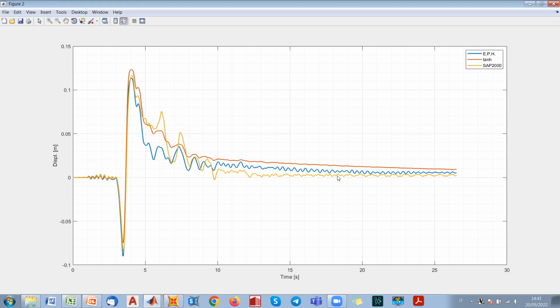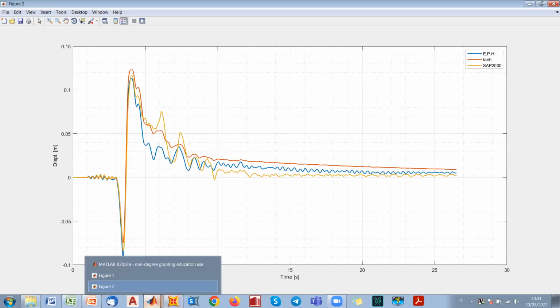And this is what I meant, actually. The elastic response of the building leads to an additional contribution for the recentering capability of the isolation system. So you see that even though we have approximately the same behavior, and we achieve approximately the same displacement here, and then there are some additional fluctuations of the superstructure, which leads the overall system to displace back to the zero configuration. Okay, so this is not always true, but at least in this case, this is what happens. And this is in general on average what happens also for other earthquakes, we are expecting to find exactly the same behavior also for the other earthquakes. Let's check.